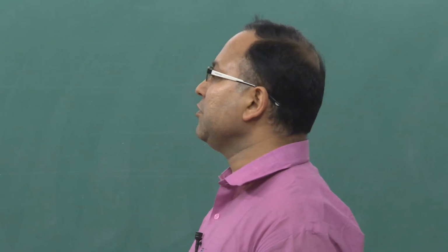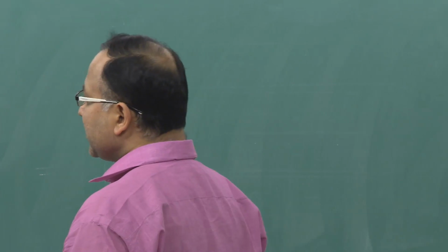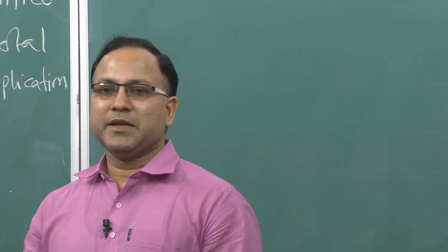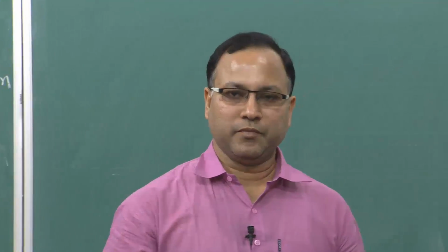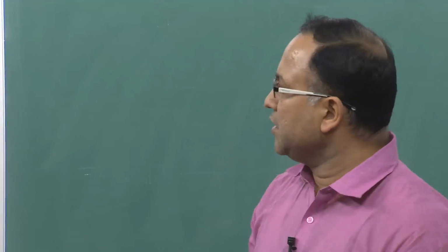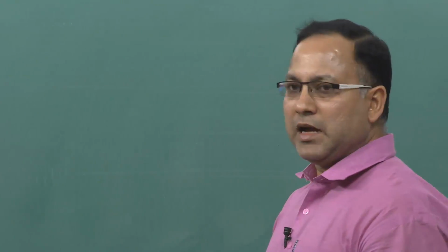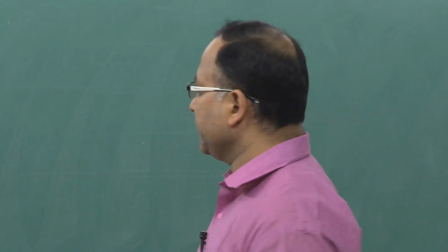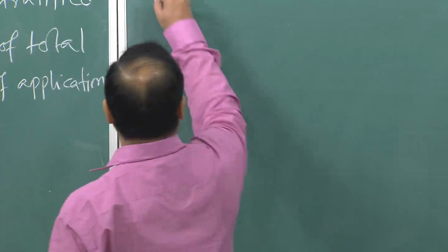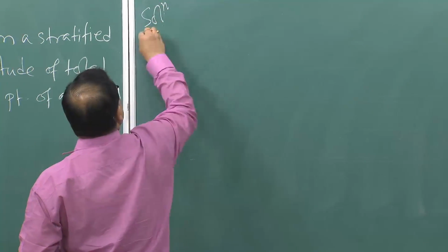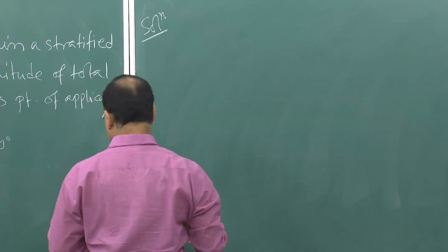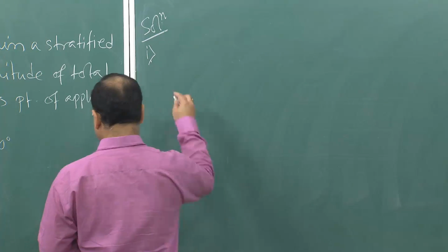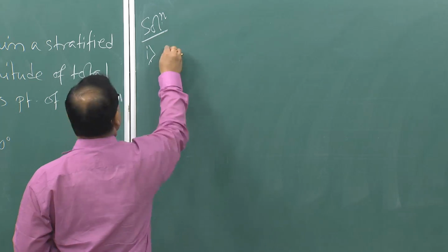That means, you may have the possibility of getting tension cracks at the top layer, as well as you will be getting some tension at the top of the wall. So, that thing you need to consider in the pressure diagram and in the total active thrust calculation. Okay. So, let us see how we can solve this. So, solution. Now, first one is sandy silt layer.